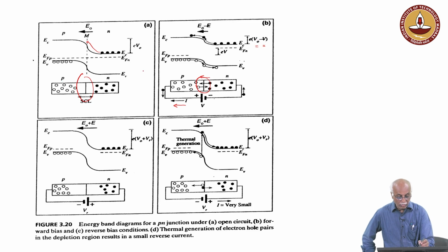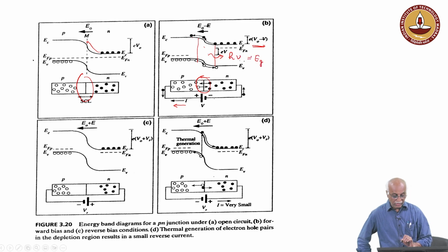So, without bias and with bias, the potential difference will change, and this energy allows the electron to cross over and go through this junction layer. When they go through this junction part, depending upon the band gap, when an electron combines with a hole, due to the recombination the photon which is generated, corresponding to this band gap, is seen as the light which is emitted.